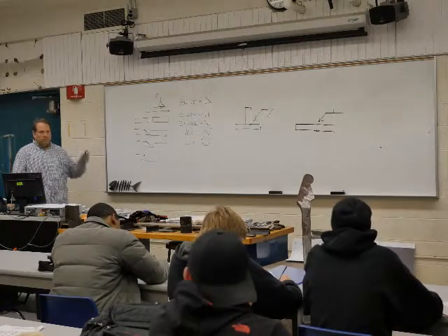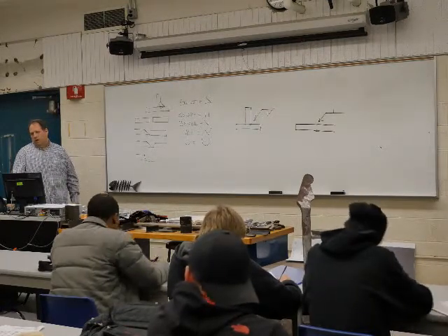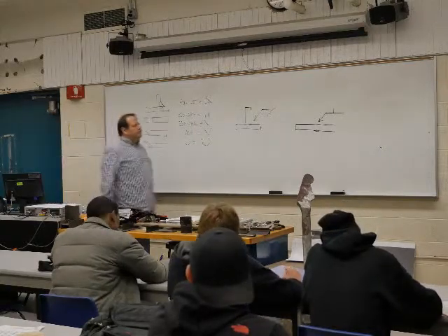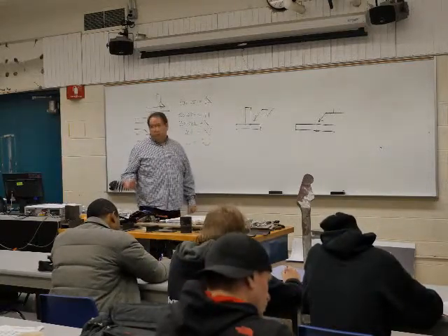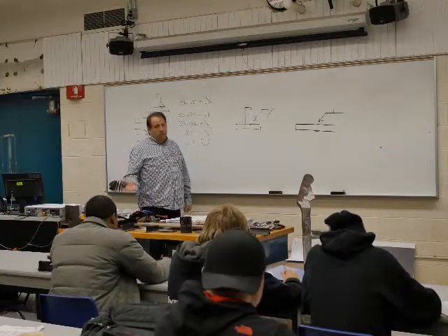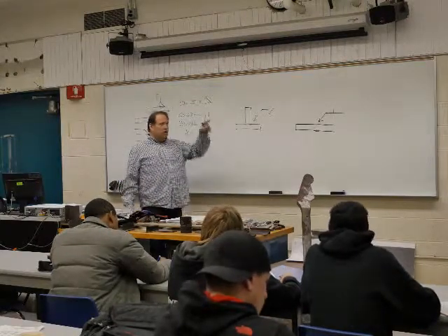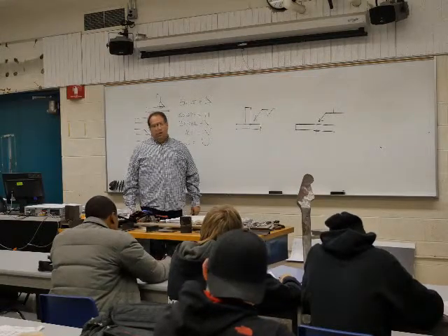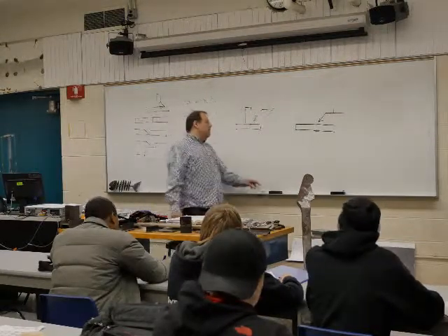So specifically, that would be arrow side. So it's a fillet weld on the arrow side. Pretty simple so far. And you know what? The majority of what you're going to run into is probably literally that easy. Okay? So let's take a little bit more.